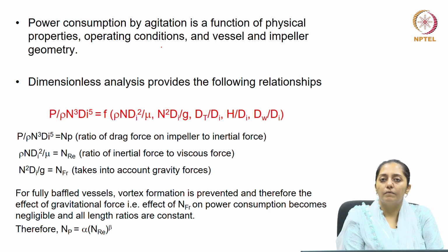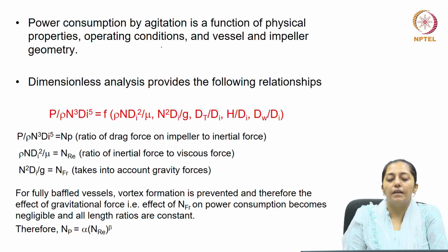Now, for adequate agitation, the power will be consumed by the impeller. So, how to determine the power consumption? This power consumption is found to be a function of various physical properties, operating conditions and vessel and impeller geometry. So, again, dimensionless analysis is used to provide these relationships.